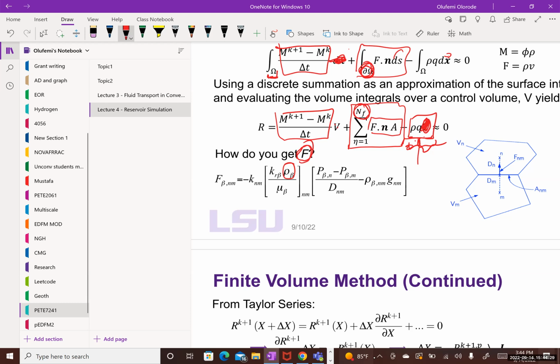So you have the pressure at the current time step and at the previous iteration, the Newton iteration you're working on. Yes. So you always use the current stuff. It's just a second loop going on. In that inner loop, you are solving for the delta X.